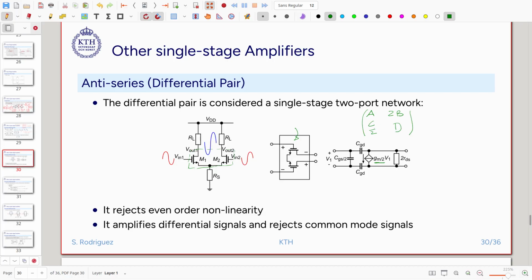We have that the transimpedance parameter has been doubled. That means the input impedance is being improved, because the transimpedance parameter depends partially on the input impedance of the transistor. Because we multiply the current by this input impedance here, we say that this stage has twice as much input impedance as the single stage.